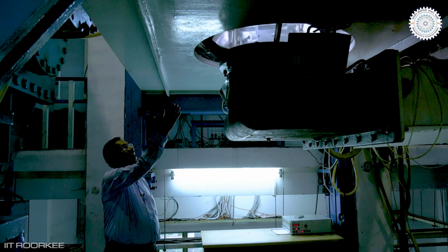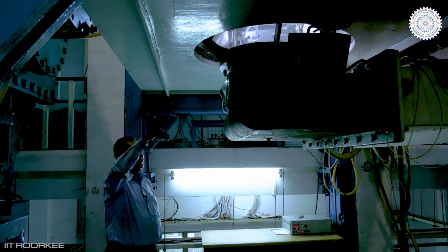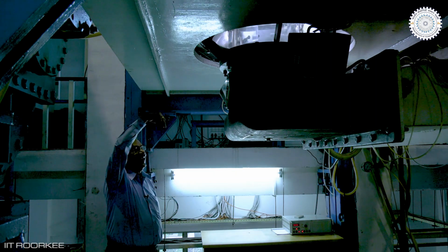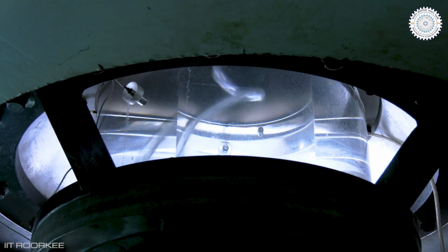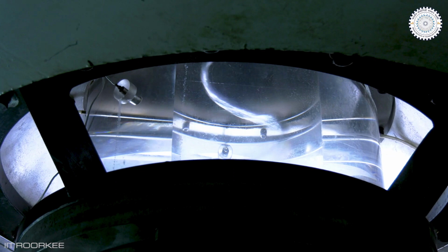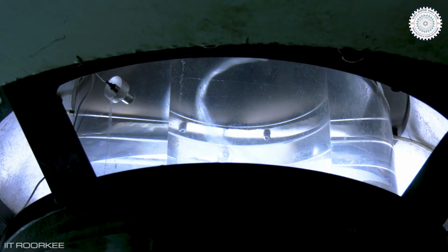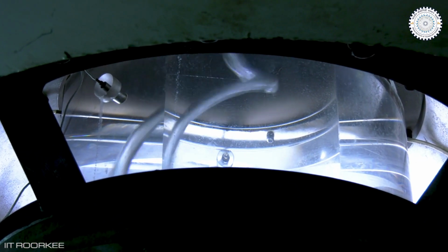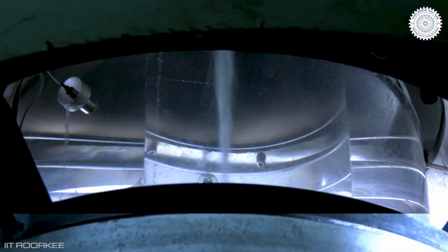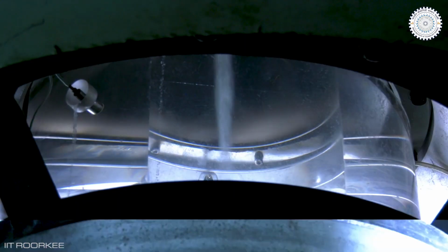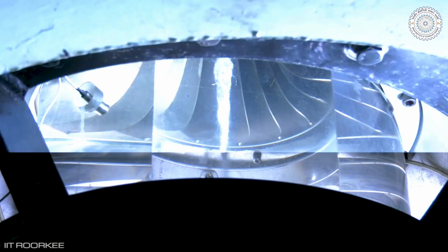Here you can see a whirling rope. You can see if we hold a rope and rotate it like this, what would be the shape of the rope? This is an intrinsic phenomena of a Francis turbine and exists between a part load of 40 to 70%. Now we can see a straight rope. You can see the difference. Now the rope is straight instead of a whirling rope. This rope is formed at overload above 105 or 110% in Francis turbine.